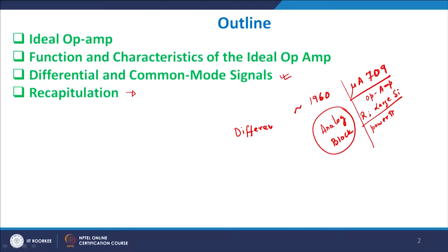So if I have two voltages, maybe two sine waves, we subtract the two and then multiply with a fixed gain value A, and that is what the output is all about. That is the reason it is also referred to as a difference amplifier. Why difference? Because it is looking at the difference of two voltage sources and finding the output voltage depending on that difference.